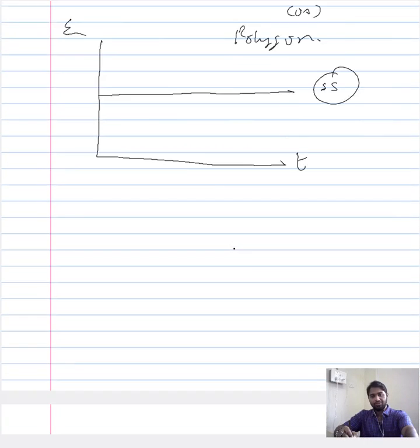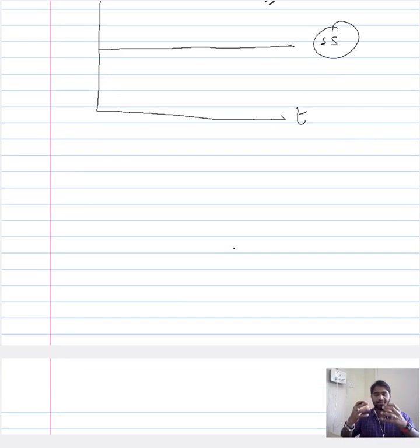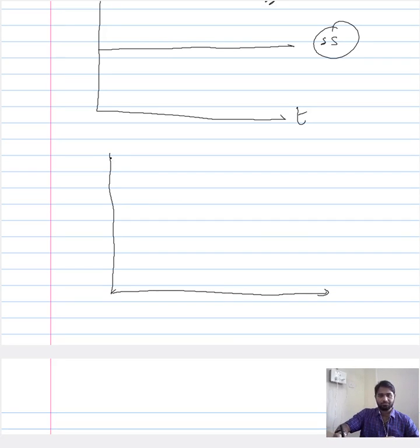Now ultimately, when the influence of the high temperature becomes more pronounced, or the plastic deformation becomes more pronounced, the plastic deformation is now allowed to run wild, then this would ultimately lead to the final stage that we saw, that is the ternary state or the accelerating creep state, and that would mean that the plastic deformation would increase, and the slope of the strain would sufficiently increase, leading ultimately to the failure of the material.